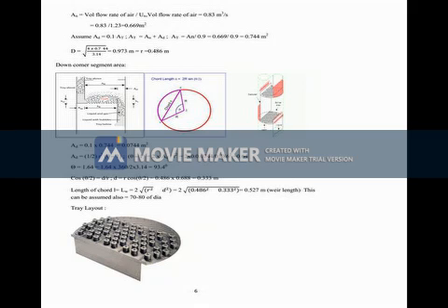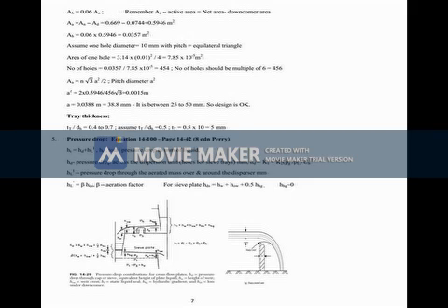For that you plot X versus Y, that is mole fraction. You need not consider mole ratio coordinates because the system is dilute. Construct the equilibrium line. When you select the axis, be careful. The x-axis should vary from 0 to 0.1, the y-axis also 0 to 0.1. Draw the equilibrium line with slope 1.68.